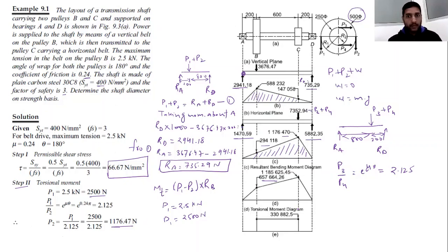Okay, बस ये ध्यान रखिएगा कि suppose there are different cases now. Suppose we are taking a case that a shaft is carrying, suppose once again, two pulleys, and both the pulleys are acting in the vertical direction, means the tensions are acting in the vertical direction. So आपको फिर वहां पे क्या करना, एक ही डायग्राम बनाना पड़ेगा. There is no need to draw the separate diagrams. आपने एक ही डायग्राम बनाना है, उसी एक ही डायग्राम में जो बैक से बेंडिंग मोमेंट होगा वो ले लीजिए, और वो हमारे लिए आसान हो जाएगा. Okay, so I hope now this will be clear to you.